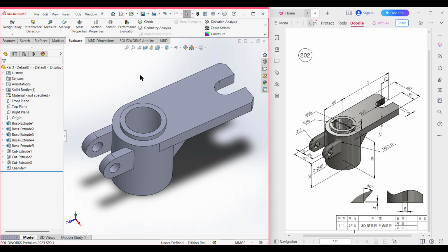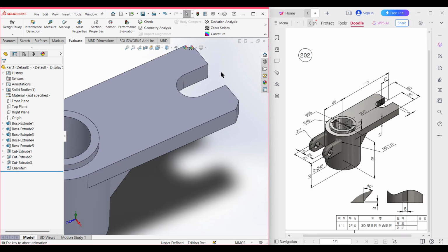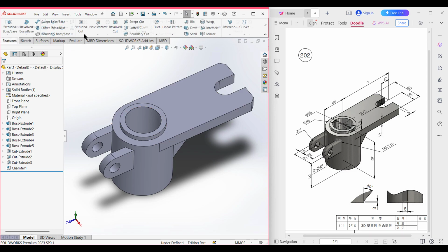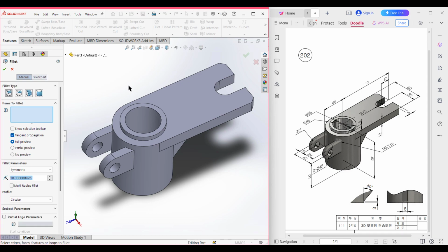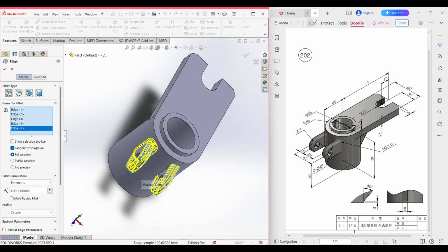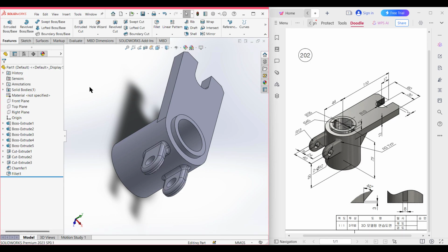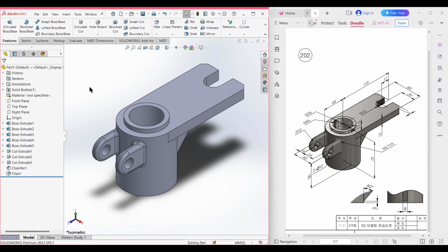Now let's go back to our sketch. You need to select by this horizontal portion. You can try out this feature by using the measure tool. Now let's go back to our sketch and select the fillet option, and we'll have a fillet of R3 radius. So dimension it to R3 radius. Now select this upper line and also select this edge, this portion, and this other side also, and select these two sides. Now press OK. Now isometric it for a better view. So as you can see, we have drawn our 3D sketch.